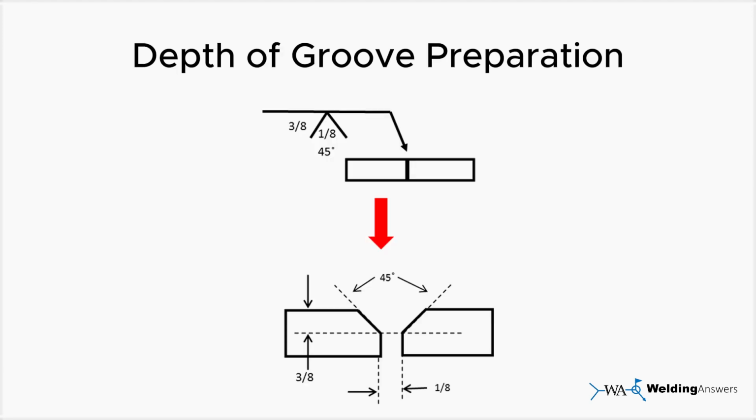Depth of groove preparation. The depth of groove preparation specifies how deep the bevel or other preparation extends into the material. This dimension is always shown to the left of the groove weld symbol.